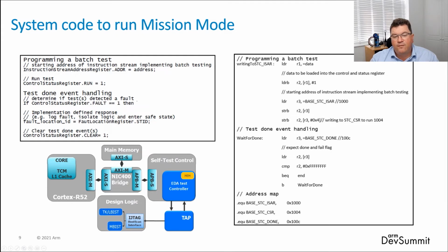So, on a full automotive device, you can simply control all of the test content within the device via your safety manager CPU. And it can be done dynamically, controlled through the software that's running on that CPU. So any enhancements or changes to the way you need to run those tests and the frequency and even the order in which you run those tests can be updated once the device is in the field by means of a simple update to the safety manager software.